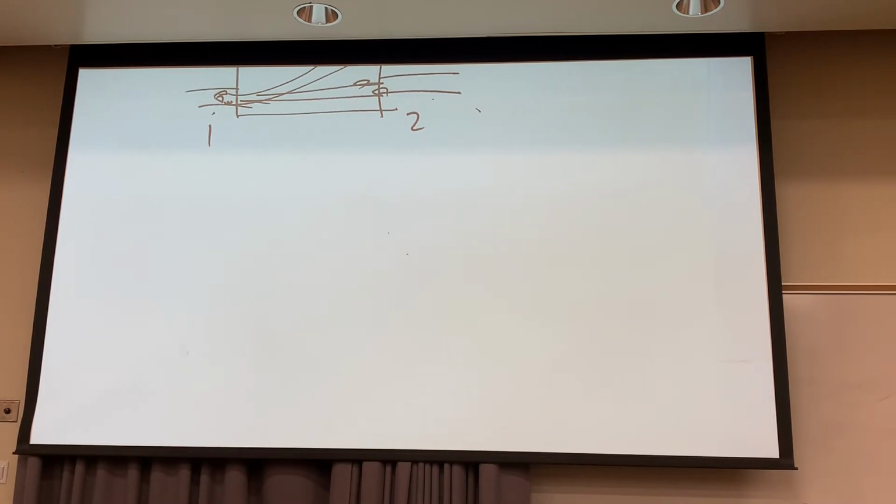and then go through signal processing. From one of them, they want it to circulate into one bank. From another signal, they want to circulate that information to another portion of the receiver, so they can data process this. And here's the deal. They know the time delay from when the signal gets there to when it gets back here. Because they know the path from when the signal was sent, at the speed of light, c times t1 would be when it hits here. Then c times t2 would be when it gets back here. That means the total path traveled would be c(t1 + t2).